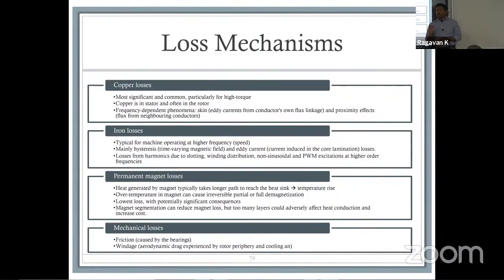So yes, there are some rules of thumb, but you would not see people defining it strictly. In general, PMs tend to be 0.8 or above, up to about 1.5. But you will also see some cases in which they select up to 2 millimeters of air gap. It's possible, especially in a high vibration environment, that a slightly larger air gap makes sense. You might end up putting in stronger magnets, which then leads to more cogging. So there's a whole cycle that you have to follow. There's a cause and effect for everything. Every decision you make has a cause and effect, so you'll have to work through your design trade-offs to decide what to do. That's a good question.